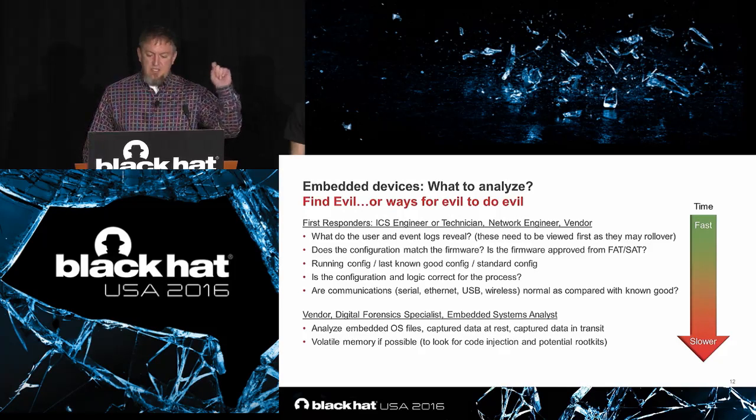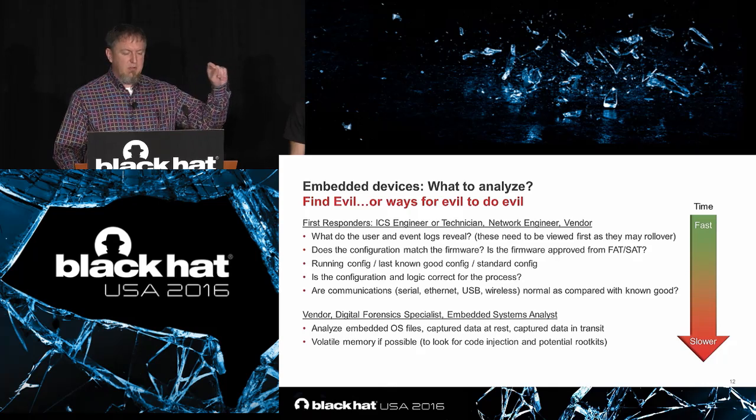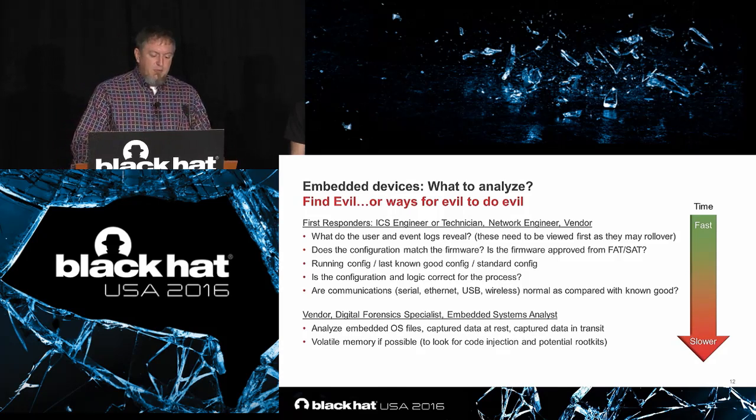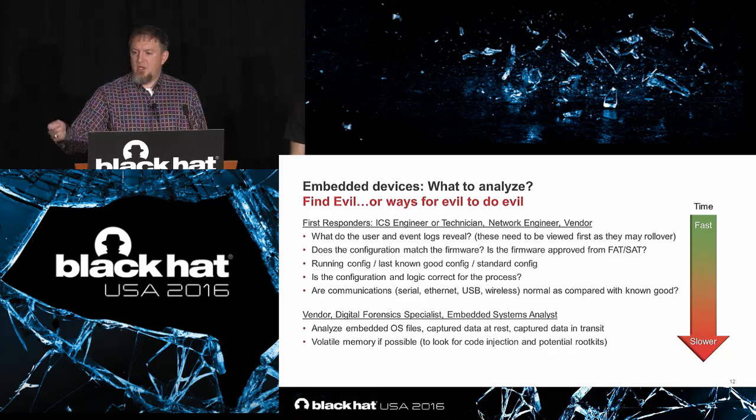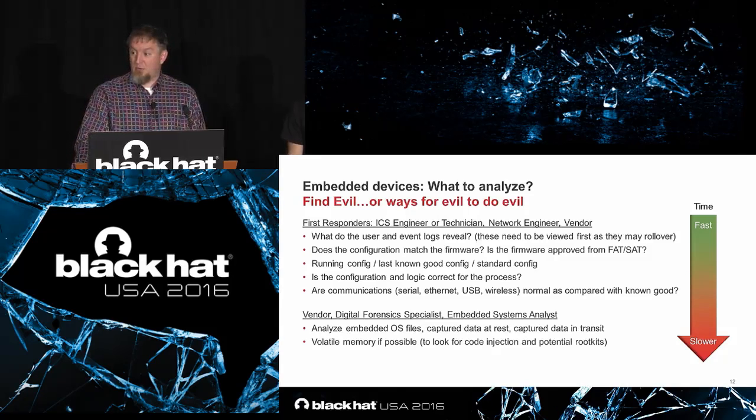The time it takes to do these collections and how to analyze these, there's things that are done fast and things that take a lot longer. So for first responders, these are the fast things. We want to get the user logs and the event logs. And in an embedded device, you may have to connect with a console cable and look, and it may only have 255 messages before they roll over. So you have to get those logs quickly before they roll over.